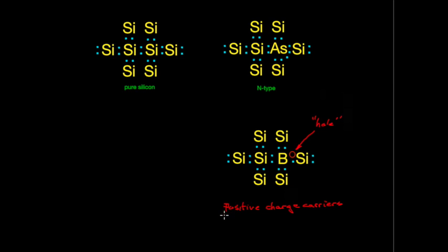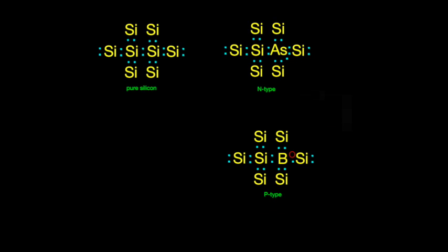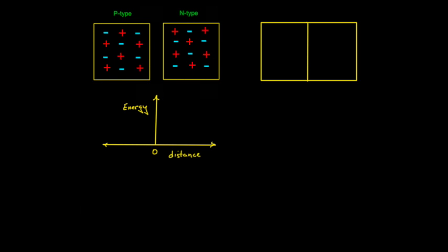We call this a p-type semiconductor because holes are thought of as positive sites. Note that both types of material are neutral overall. Interesting things happen when we bring p-type and n-type material together. Some electrons from the n-type material move across the junction into the holes in the p-type material, creating a net negative charge along the interface. At the same time, they leave positively charged atoms or holes behind in the n-type material. Eventually, the charge builds up to repel any further jumping across the border.